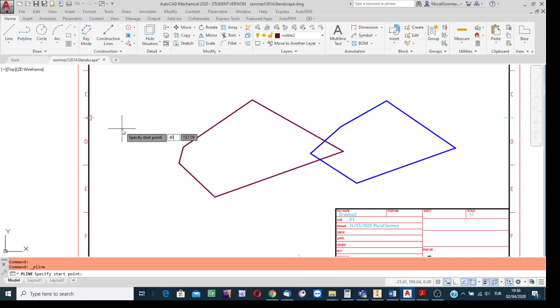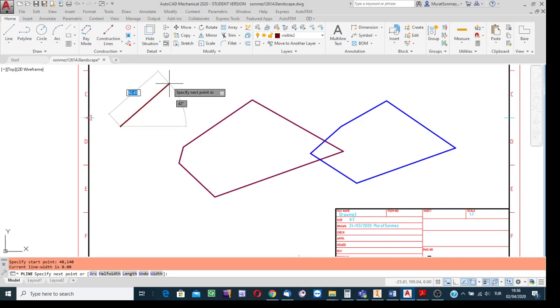Okay, 40. Click on the comma key, 140 is the ordinate value. Press enter. And yes, the simulation has started. The first point is at the place for which I input the x, y values. And now the line is to be created. Although in the simulation it is obvious that the system is ready to take a number as the length of the line, in this example say that I don't know the length of the line.